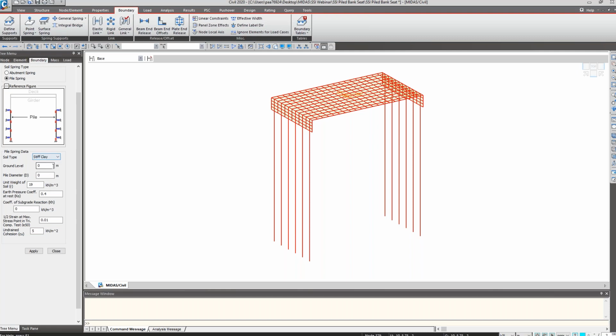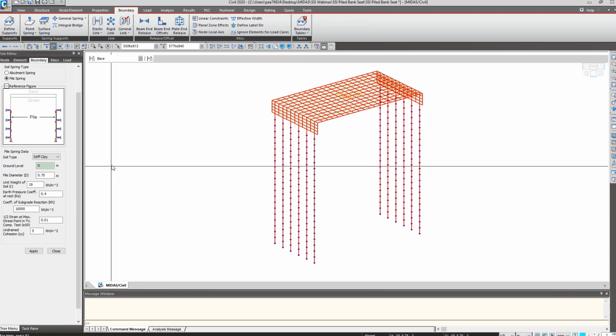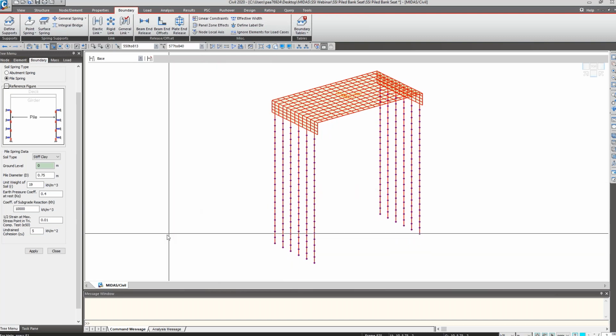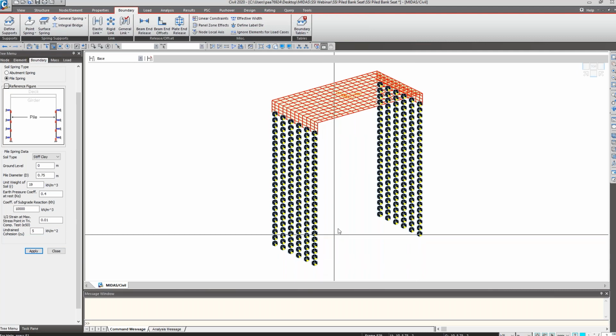And then with these definitions, defining the ground level, the pile diameter, that we have 750 mil diameter piles, density of the soil, and a number of different parameters, we can just apply that directly to all our springs, and Midas automatically will calculate the different depths of the nodes, and depending on the coordinates of the nodes, we will implement the relevant PY curve. We do that, then we have all these nonlinear springs at the different levels.